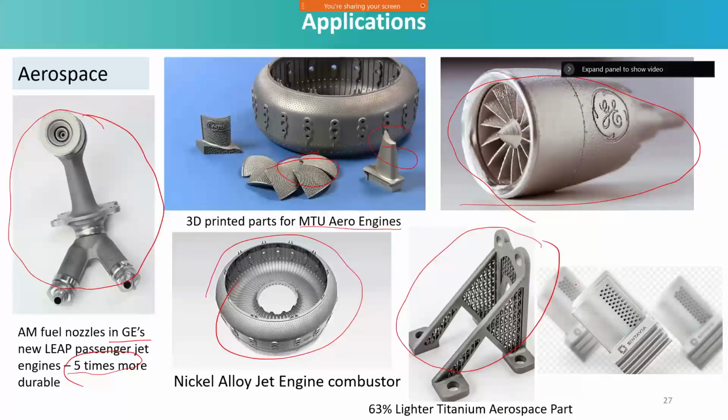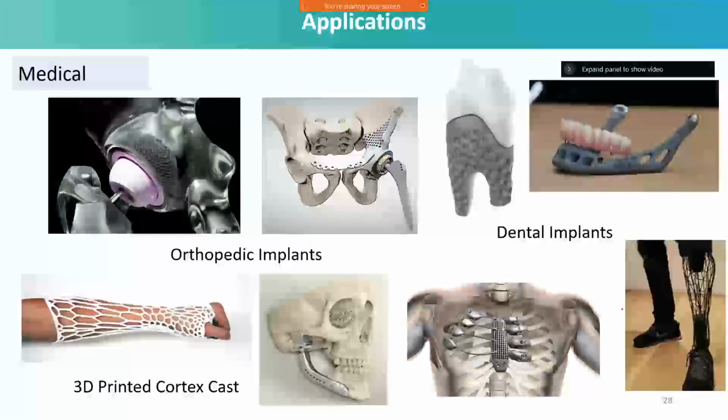And this particular firm started producing turbine blades with cooling holes imprinted on them, which is very, very complicated if you are doing it with a conventional process, where micro EDM drilling is used. Again, there is a limitation in producing curved holes. But here, in this case, you can produce a curved hole.